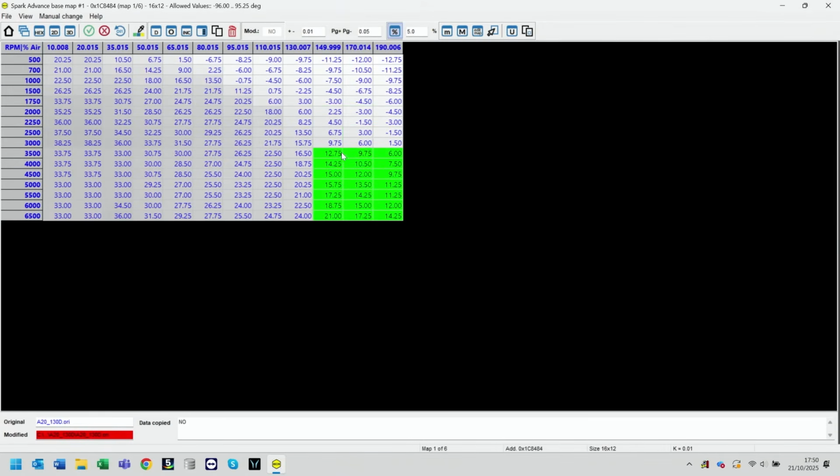So when it comes to timing on a gasoline turbo engine, it's going to be very small changes, maybe half a degree or a degree at most in this bottom right-hand corner of the table, just as that final extra tweak to the map to get the best out of that stage one. It's got to be running on really high octane fuel and in good operating conditions with a good service history, if you like, on the car. If it was a naturally aspirated engine, we'd typically be looking around about 3 degrees of timing, and similar for supercharged engines. And we'd be looking at a slightly broader area of the ECU table to make those changes on.